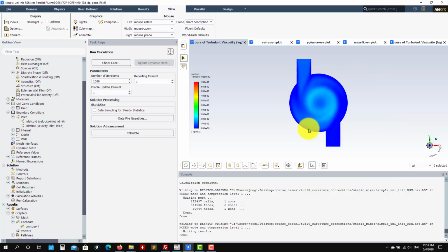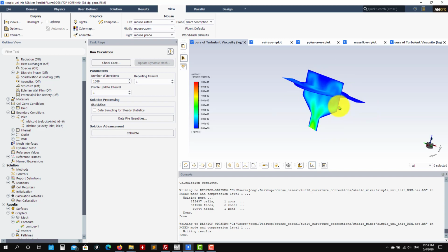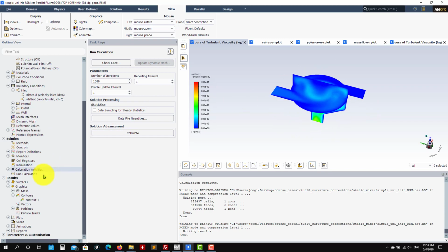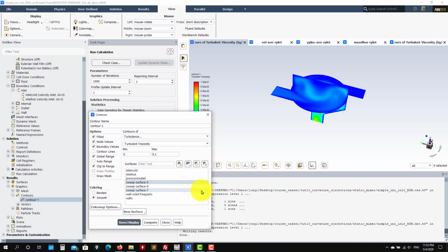So this one here is the Reynolds stress model, which we addressed in the last lecture. See that we're seeing here the turbulent viscosity, which is related to the additional equations that you are solving, the epsilon equation, and also the K equation, where you take the trace of the Reynolds stress. But when you analyze this one, you shouldn't look at this too much. Instead, you should look at the information of the Reynolds stresses, because you have that information available. So you have it here, and you have all your Reynolds stresses. Look at that information instead of this viscosity.